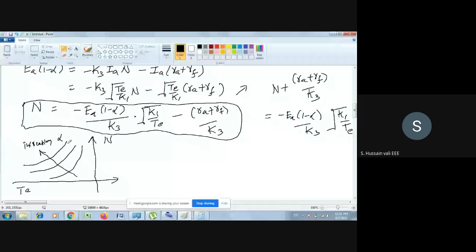Okay, so you get power negative here also. Even in this case also you get power negative. So if you get power negative, then that's it. So you will find out that it takes back. So this is the torque speed characteristics. It is in regenerative way.